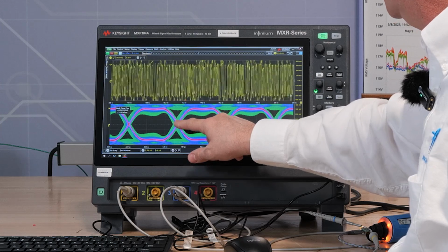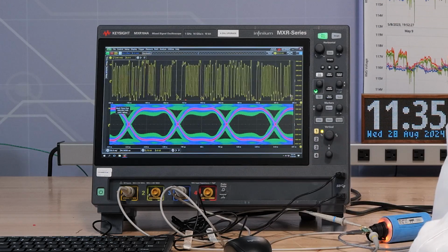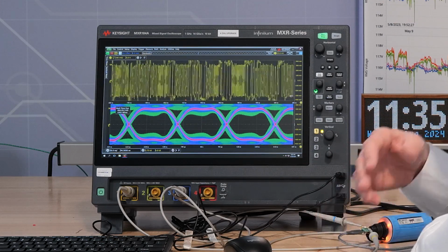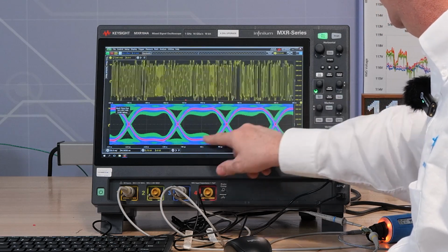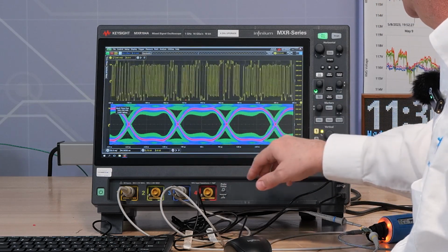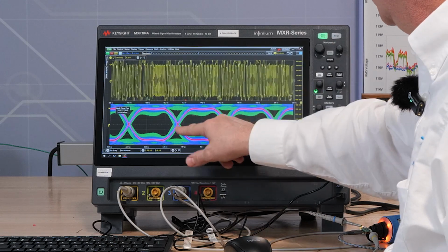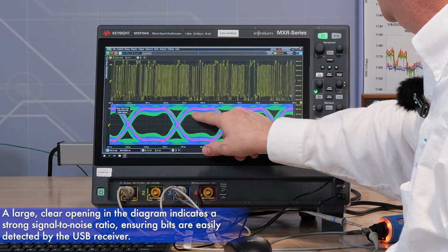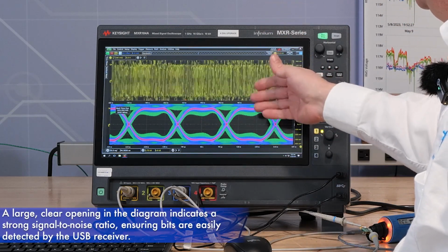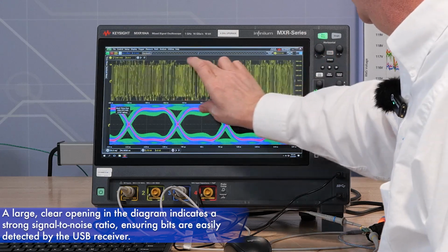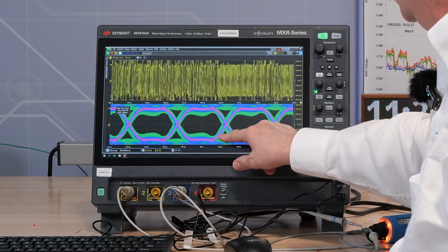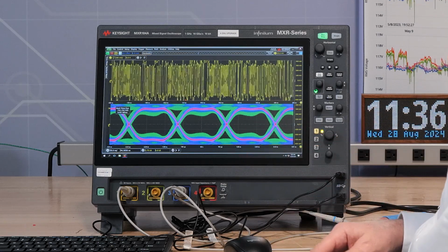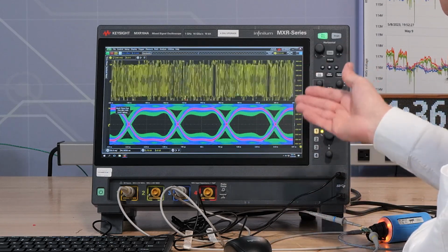And we're also looking at the rise time. With the 2 nanosecond pulse width, the rise time should be in the fraction of a nanosecond range. We're seeing good rise times here in the tens of picosecond range, given the time scale on this axis. So we have a clean eye with a wide open center and sharp rise times as determined by the scope, looking at a composite of many thousands of bits flowing through. You can also look at the thickness of the eye to gauge jitter. The clock is embedded in the data stream and the USB receiver is doing clock recovery.